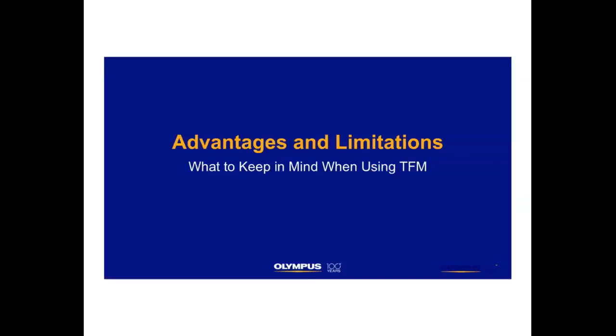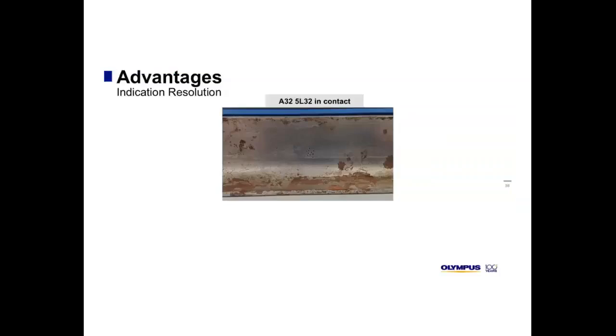Now we move to the advantages and limitations of TFM. First advantage, which is very obvious and everybody is talking about, is the indication resolution. So here we are using a 32 probe in contact on a carbon steel block with small holes that could represent porosities.